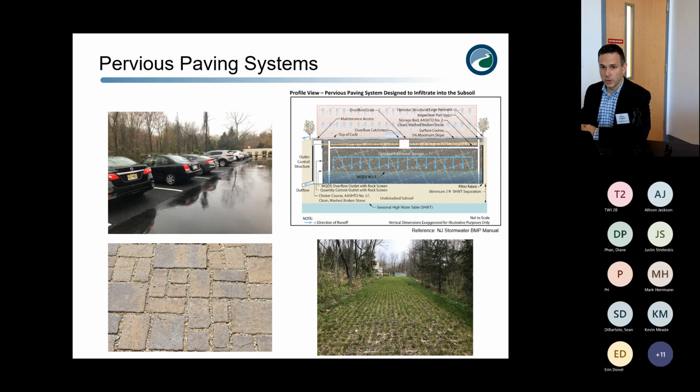where those blocks have soil in between where grass can actually grow. A lot of times we'll use that for different types of applications where there's not frequent road traffic. So the bottom right picture there is for a pump station where the municipality needs to access the pump station for infrequent maintenance. So they might use it once a quarter, but they'll need to get a vac truck through to suck out stuff from the pump station. So that provides a way for them to access it safely, but also have that pervious component to it.